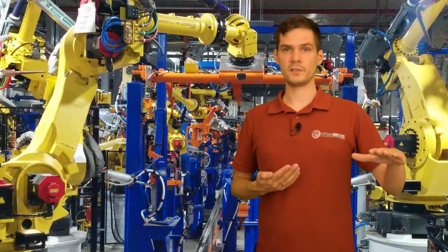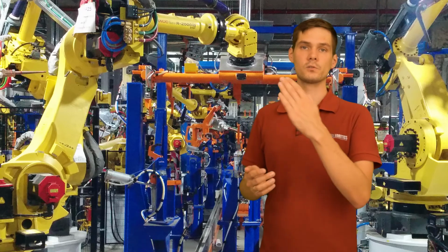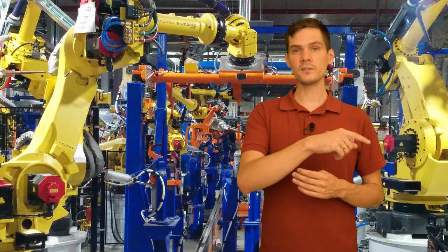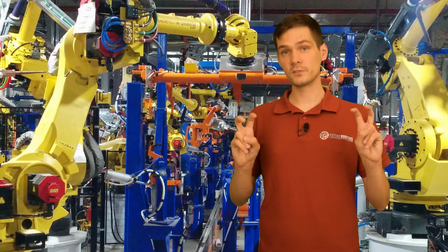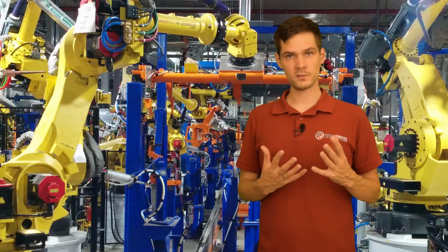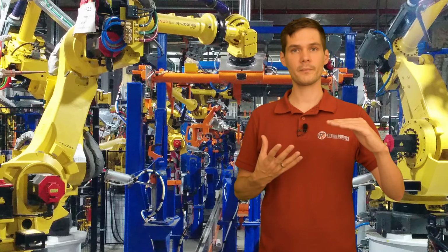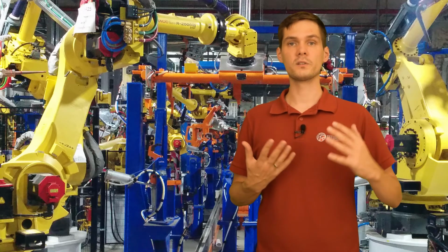Also, why are you using it? So when you are at the bar and you go to the bar itself or to the restroom, you will always go back to the same point and you know where your 0 is. So it's the same for the robot. You want to refer all of your movements to one point. So it's easier for you to track the robot program. It's easier for you to understand what the robot is doing.